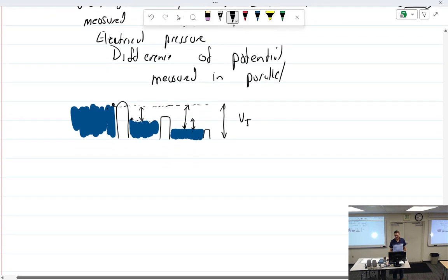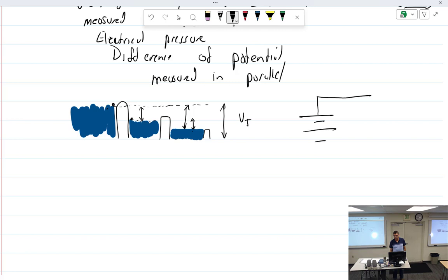And that's why when we take any sort of circuit, and we can say this is 12 volts, and we'll just do a one element thing right here. We can't say, well, what's the voltage right there? We can't say it's 12 volts. It's always as compared to what? What's the voltage there? The next question is, compared to what? So the voltage right here compared to the voltage right there is? Zero, because there's no difference.